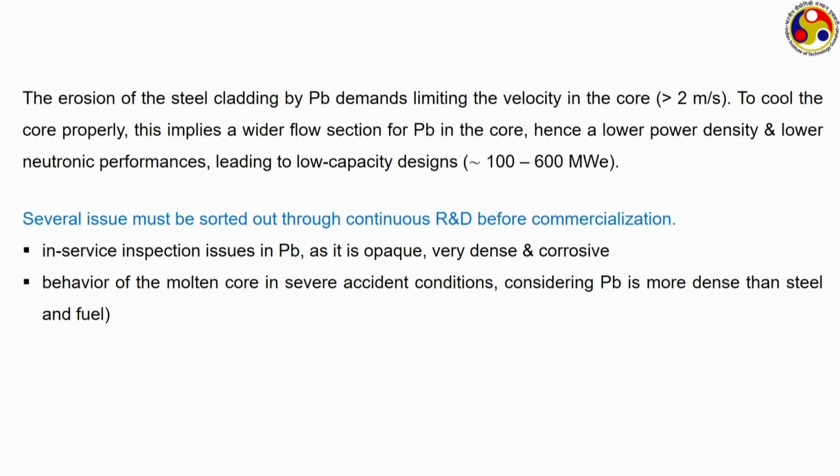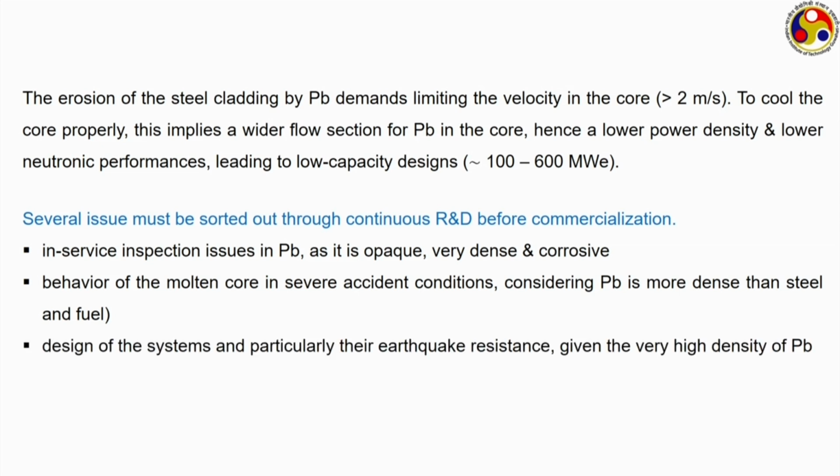Particularly, we have to consider that the lead is much denser compared to both the fuel and steel, which is the cladding material. The design of the systems and particularly earthquake resistance, given again the very high density of lead, can be a factor there. And finally, aerosol management, washing and decontamination techniques need to be considered.